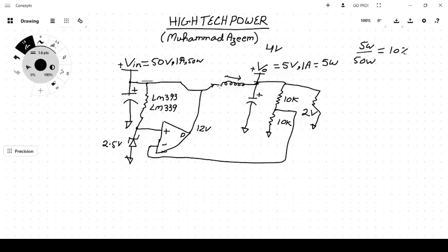So although we have solved the dissipation problem of the output filter capacitor, and it is operating now at a higher frequency as well, so the components would be less bulky, and the efficiency would be more than enough, maybe 80-90%. But now the issue has occurred that the current is lagging in the inductor, and when the transistor is stopped, the current is saying that I still have to go through the path to complete, so that I become 0.